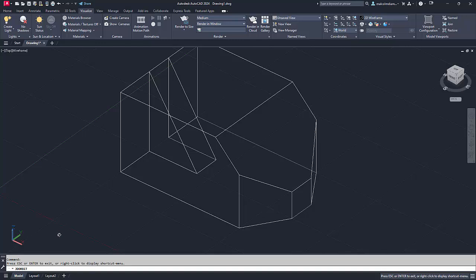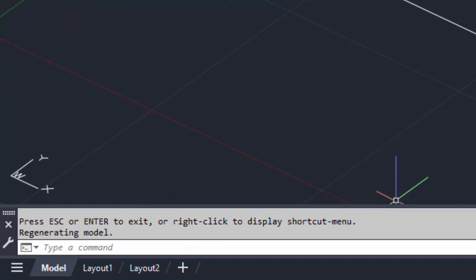And the reason I can't do that is because you can only extrude an object like a circle into a cylinder, which would be representative of a hole, in the positive or negative direction of the z-axis. And you can see at the moment it would simply just come straight down. So I'm going to get out of the 3D orbit that I was in by hitting the escape command.